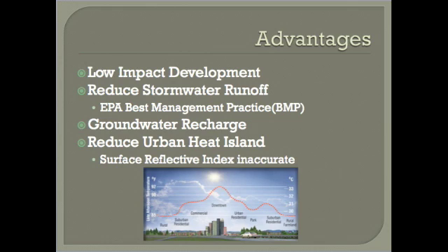Pervious concrete reduces stormwater runoff and captures the so-called first flush of surface runoff. This first flush is the first time it rains after a dry period. During the dry spell, pollutants such as oil from cars build up on the surface of the concrete. When the first rain comes, those pollutants are washed down into the soil. The soil contains microorganisms that can break down these pollutants as long as the concentrations are low.